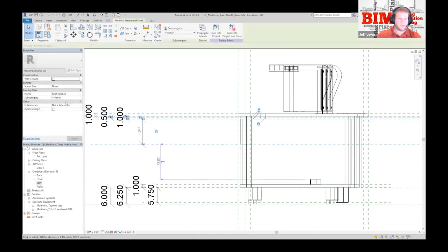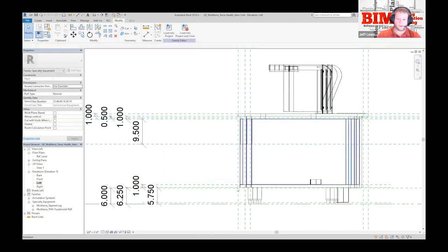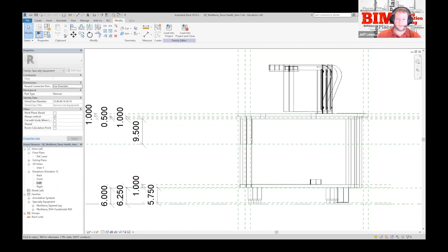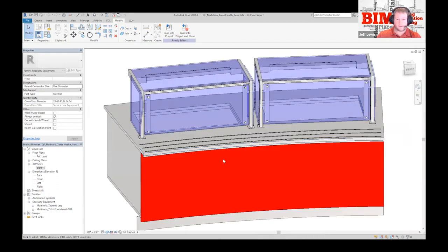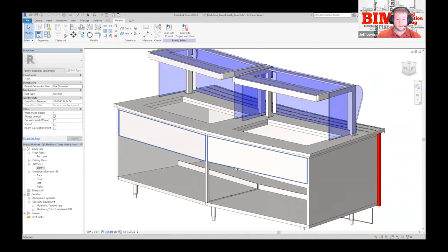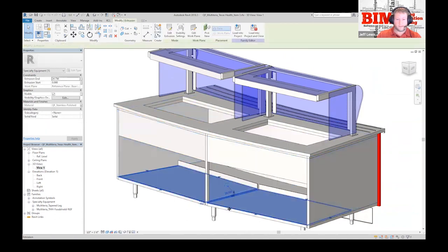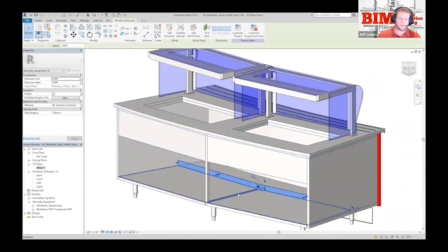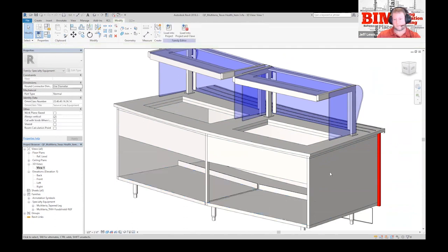And you can notice I used no reference. Naming the reference plane only helps because you are drawing from the bottom up. The feet, as we notice, the tapered legs are nested because they're being used all over the place. But everything else on this piece, as you can see, is a straight back, which gives the ease of drawing. Now, when you copy this over, you can actually reuse these, so they're going to be the same. You just move them over to the reference planes, or at least the extrusions there, and you redraw the extrusion.